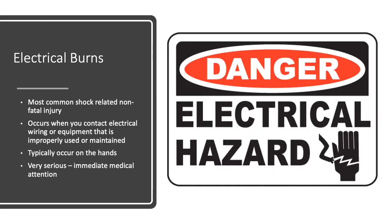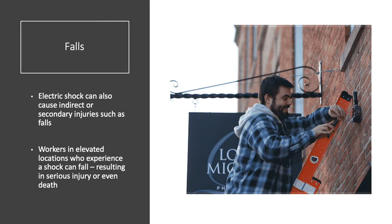Electrical burns happen typically when a shock occurs. Wherever its exit point is, and sometimes the entrance point, it will cause a burn. The heat is more than the skin can take, and it will damage the skin tissue. It will damage bone. It will damage muscle. It'll heat up your blood, for goodness sake. So there's a lot of serious stuff that can happen when getting electrically shocked. It can also cause, as I mentioned before, indirect injuries and follow-on injuries such as falling.